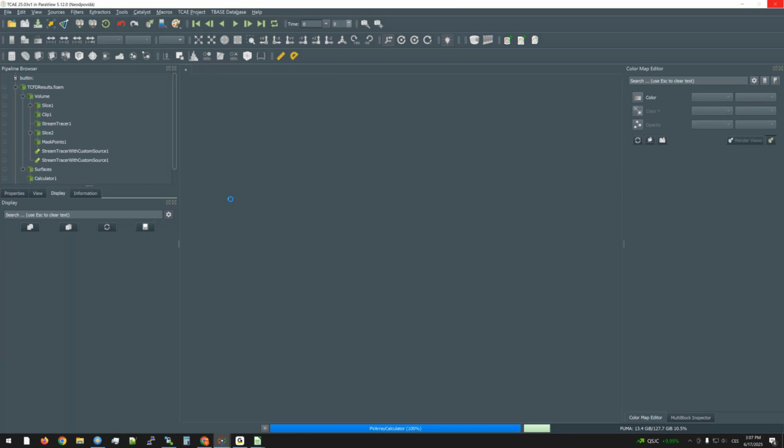So this is good to keep track of what you have visualized. And for example, sometimes if you put in a lot of filters, it can be memory hungry, so it can crash ParaView because of memory leakages, or basically because all your memory runs out.